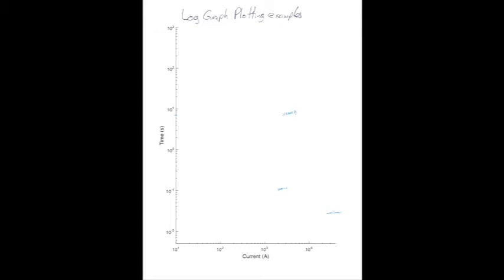And we are looking for 15,000 amps. We have 10,000 amps, 20,000 amps. So we know we're between 10 and 20,000 amps at the 3/100ths of a second line, which we had identified. Better not use commas there, it could be confusing.